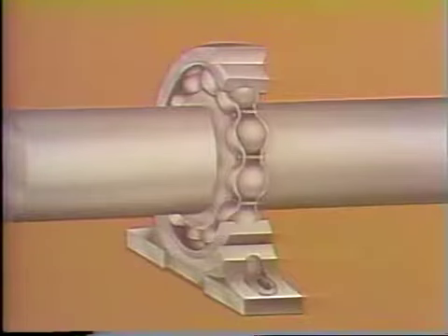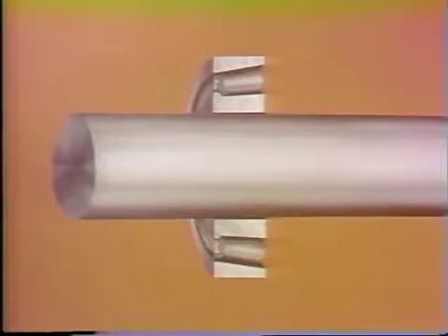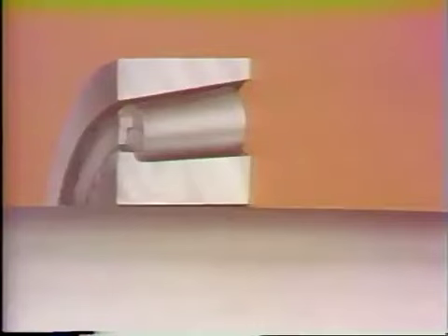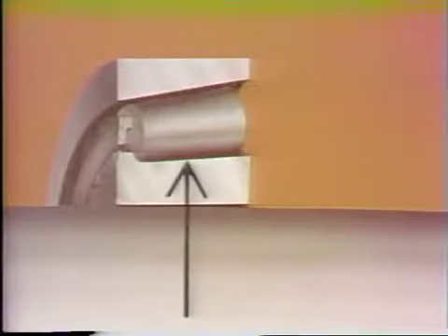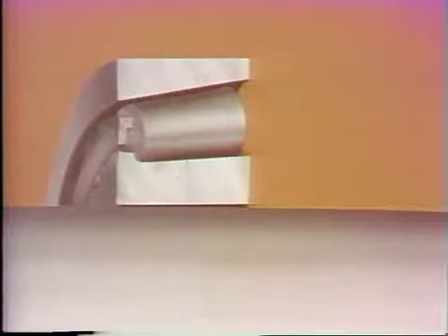The arrangement of the rolling elements between two rings maintains equal distance between the rings and prevents radial movement. Now, here's a cross-section of another type of rolling contact bearing called a tapered rolling bearing. It can handle both radial and axial movement. This ring is stationary, and this one moves with the shaft. The tapered rollers keep an equal distance between the two rings and prevent radial movement, just like the rolling contact bearing we saw earlier. The tapered rollers also prevent axial movement.